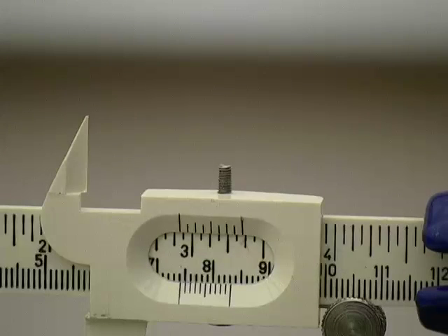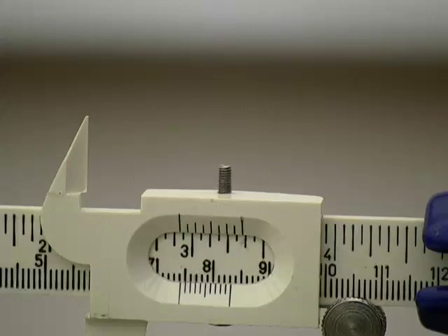This is D2 for the material Lexan. And as I told you, I am not going to measure the ambient heat for the next material. That means this diameter can be used as D1 for the next material. Alright? Well, we will measure that anyway because it's going to take me a couple of minutes before I set it up. So we will measure that diameter again.